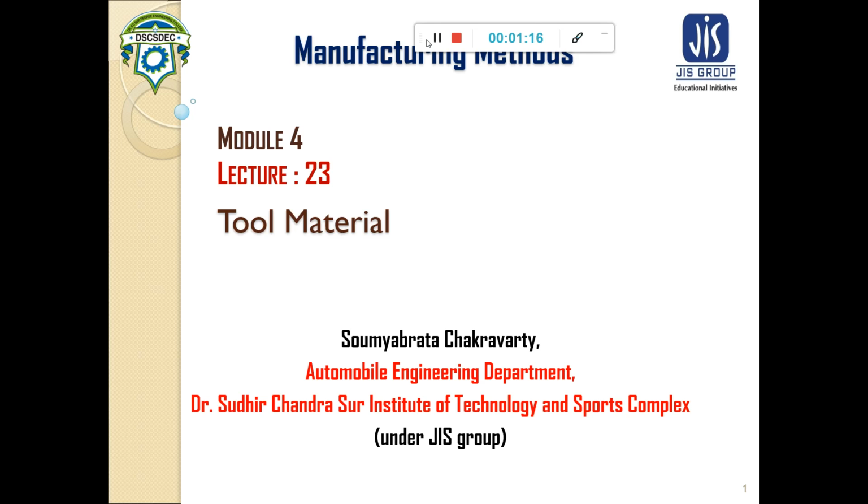So indentation is important, and this indentation can be achieved only if the cutting tool material is harder than the workpiece material. From this we can have an idea of what the cutting tool material should be. The cutting tool material should always be a very hard material. So hardness is the important criterion for tool material.